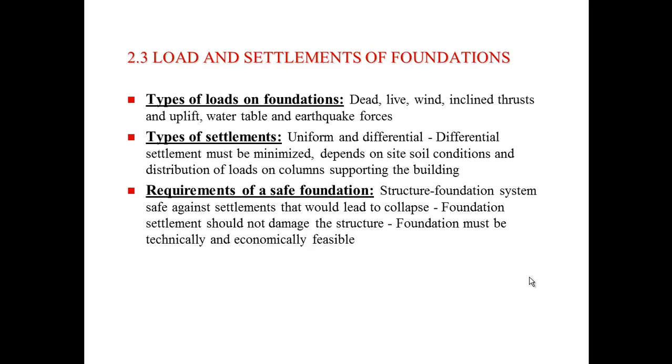Differential settlement, on the other hand, is where part of the building might be on a solid piece of bedrock, the other part may be loaded differently on less supporting soils, and part of the building could sink or rise while the other part stays stable, causing some structural damage and, at the very least, wall cracks and things like that that could cause issues.